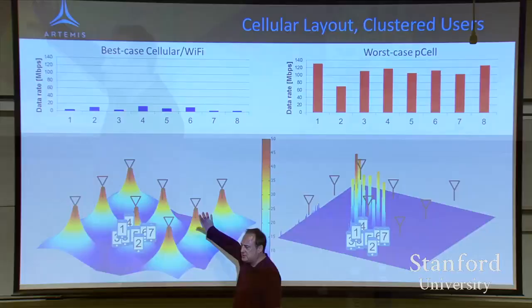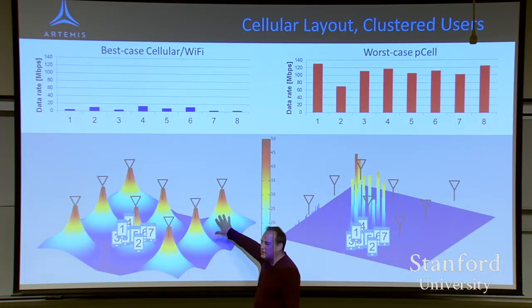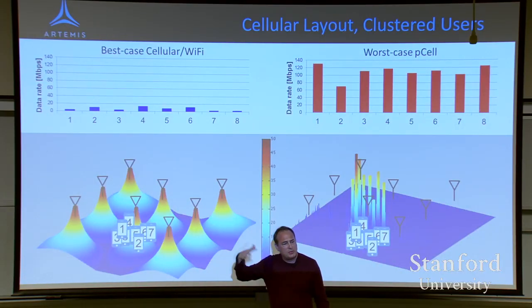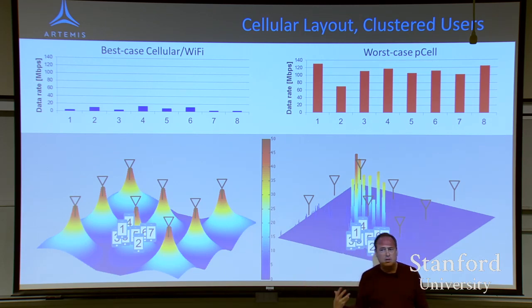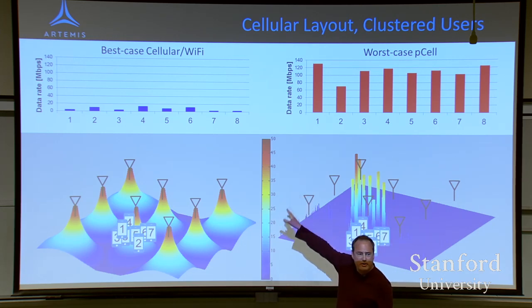There's a variety of techniques that can be used to statistically combine the signals. I do know this, that when we're doing the uplink, the received signal to a given one of our radio heads can be below the noise floor. Yet the aggregate of the signals can allow us to resolve the signal. You mean for the pCell, because that's the Wi-Fi, right? No, this is cellular. Cellular and Wi-Fi, it works the same way. So the maximum ratio combining is part of what your pCell technologies do.